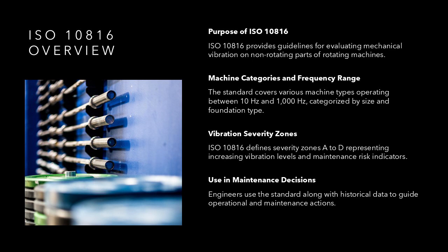This slide introduces ISO 10816 as the primary reference standard used in this presentation. ISO 10816 is an international standard that defines guidelines for evaluating mechanical vibration of rotating machines when measured on non-rotating parts, such as bearing housings. The standard applies to a wide range of industrial machinery, including electric motors, pumps, fans, and compressors, typically operating between 10 Hz and 1000 Hz.